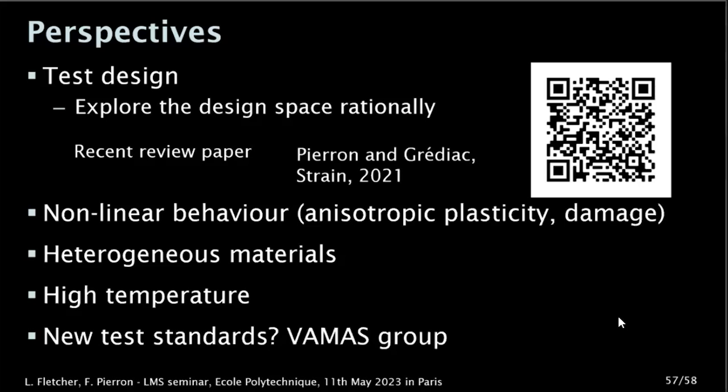A number of things would be nice to look at, obviously non-linear behavior, anisotropic plasticity would be something also quite fun to do. Heterogeneous materials, now that's quite challenging because, as you have seen, we lack spatial resolution. So we probably need something like a finite element assisted procedure where we could estimate the sort of low pass filtering effect that a measurement has by itself.